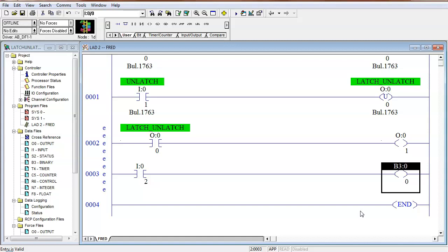So we call these internal coils. You've only got 6 outputs, and I've seen people do this. They'll use an output, and they say, well, I don't have any more outputs, because they assigned an output to a coil that doesn't need to generate an output, right? You understand that? So these are what we call internal coils. Every PLC's got them. They give you the ability to use a coil to make a decision inside your circuit, but it doesn't need to turn on a light, turn on a motor, or energize a solenoid. It's just in there to make a decision. And we call these internal coils.